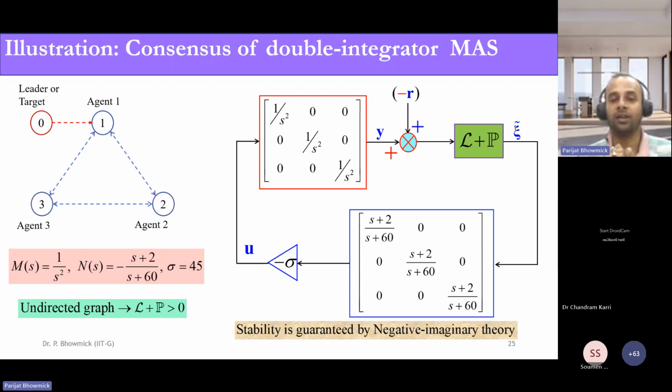Another difference with respect to our classical control scheme is that this particular configuration works with positive feedback, not with negative feedback. The proof is also there, showing why it works with positive feedback. Accordingly, you must have noticed that the reference quantity here is not simply R, it is the minus of R. Why? Because unless you take the minus sign, Y will not track R. Here the error is going to be Y plus R, right? Because it's a positive feedback case.